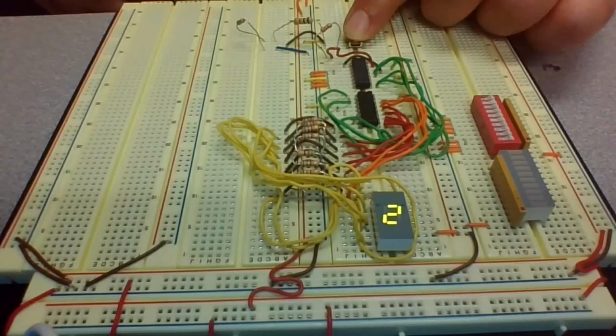That's the reason it went to 2. So again, release, 3, release the switch, 4, release, 5, 6, 7, again bouncing switch, it actually counted 3. So next should be 8, next it actually counts 9, 1 and 2 very fast because of the bouncing switch.